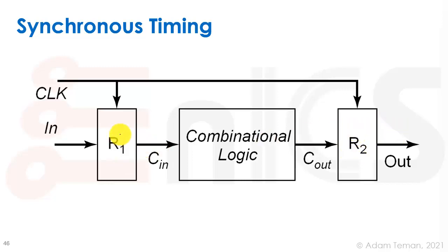Again, the system will have many of these. There are going to be many registers whose outputs go into a cloud of combinational logic, and there are going to be many outputs of the combinational logic that go into registers, and there are going to be lots of paths. So if this was a bus of many flip-flops, things are going to be running around, reconverging through this logic. They're only going to be going in one direction. There are going to be no combinational loops. Nothing's going to feed back inside the combinational logic, but things will reconverge. So you have different paths going through here, and the paths will come out at many places.